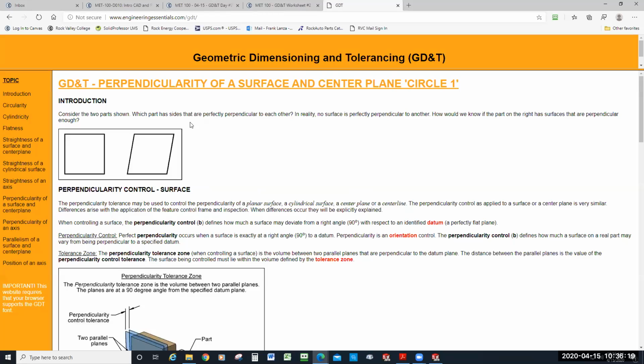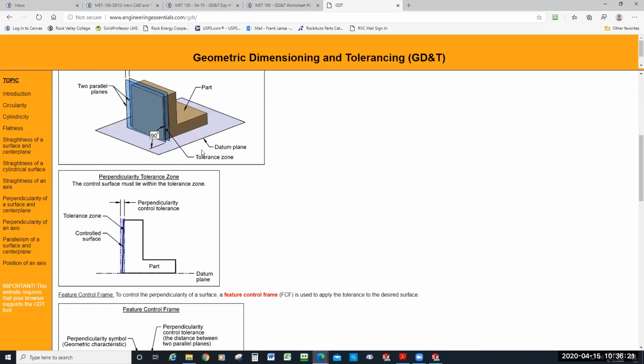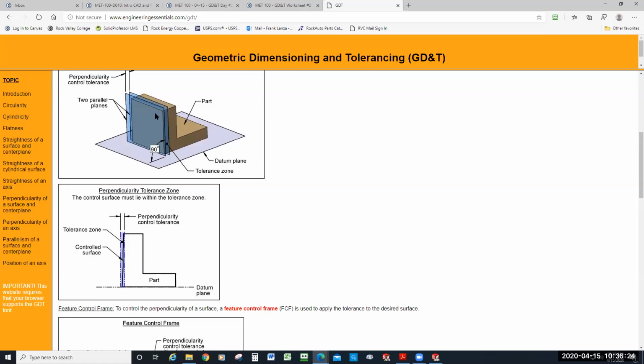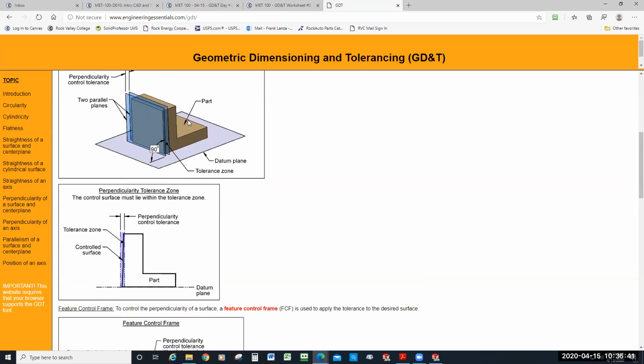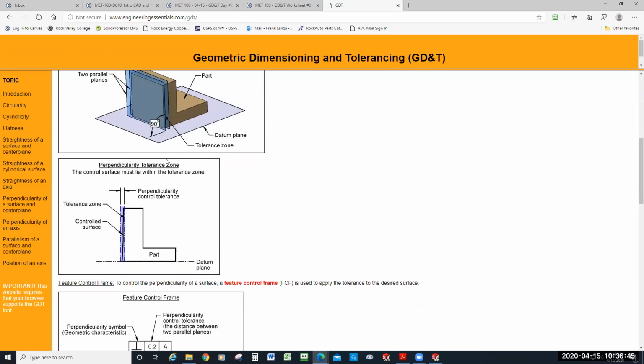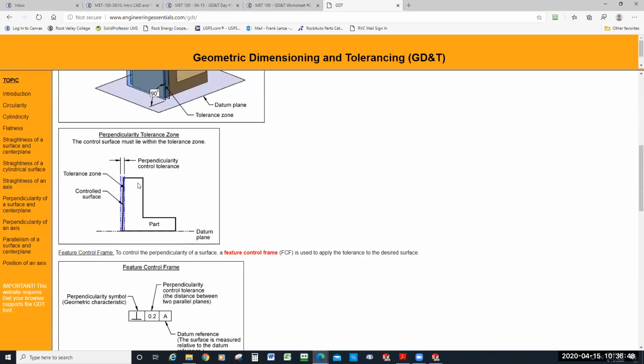I mean, if you do it in a 3-dimensional form, it'd be great, because in effect it is a 3-dimensional tolerance zone. It does have length, width, and depth. So you know, this is for your own benefit. If you draw it out, it will maybe reinforce understanding what it looks like. But otherwise, if you draw the tolerance zone and make it look like this, that's fine.